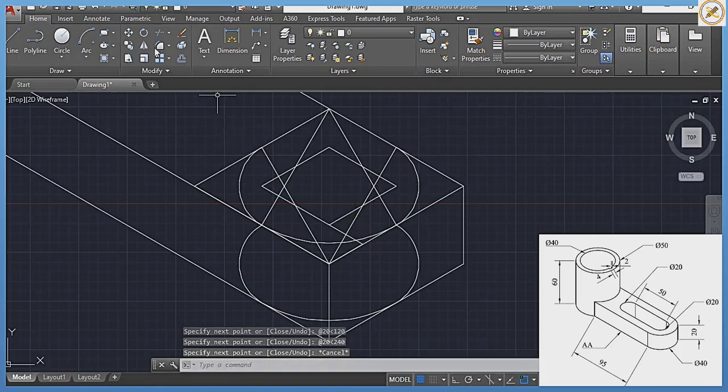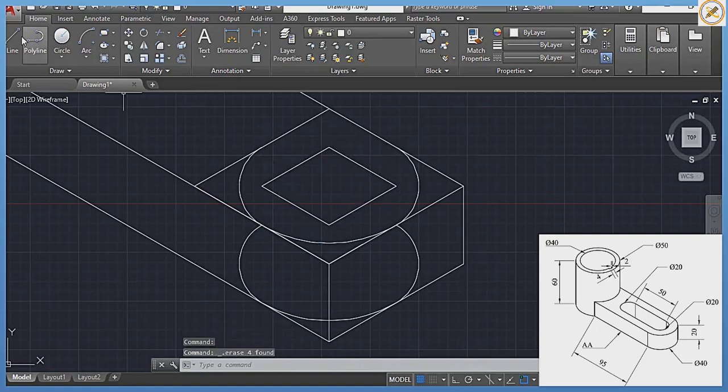Let me trim the areas I don't need. Clicking on my trim, I click on this, enter. I remove this. Picking my line, going forward I won't need this and this, so I'm going to remove them. Now I'm going to pick my line. Standing right here, I need to locate the midpoint here also. Midpoint settled with my line right here also. From here I'm going to locate the midpoint right there, settled.